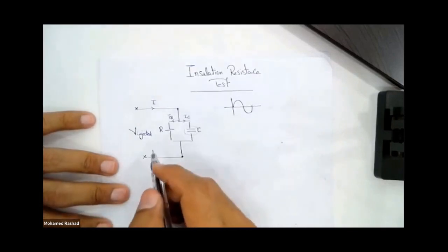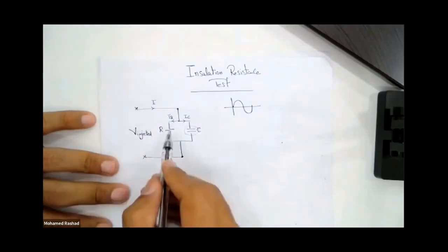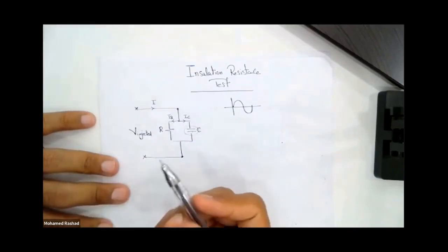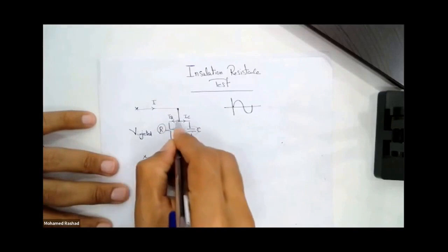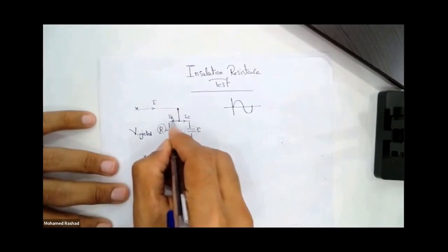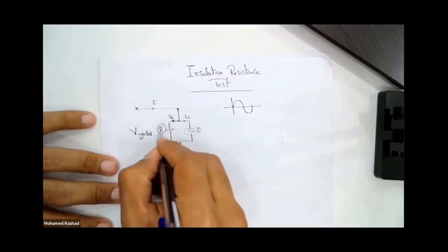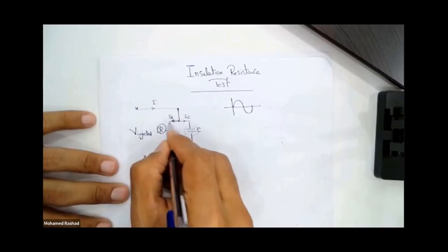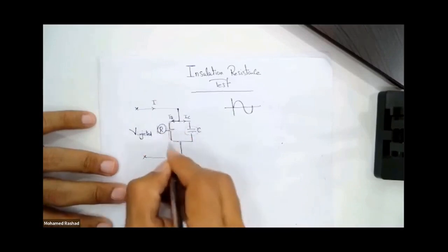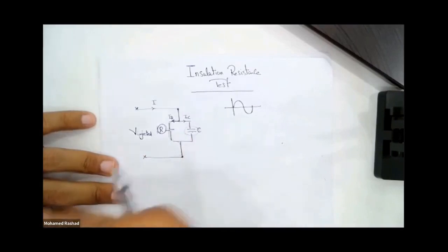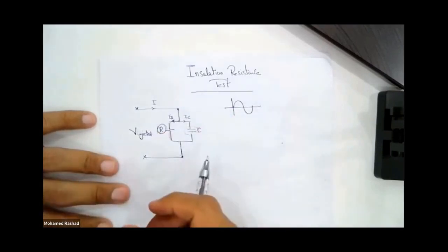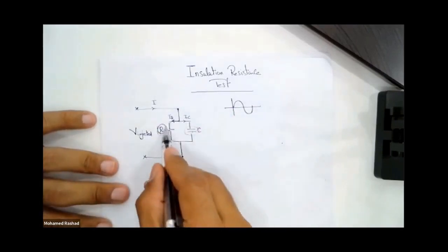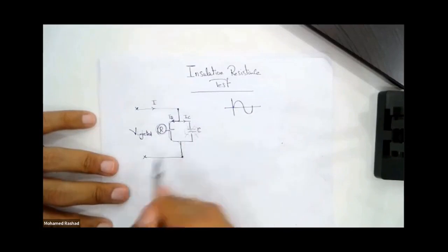Very nice. Okay, excellent. So what do I want now? I'll tell you what I want. Quite simply, which one of them indicates that your insulation has a problem? The leakage current. As long as this leakage current is drawing current from you, the lower this resistance is, the greater the current passing through the insulation will be. And consequently, what does this mean will happen? Breakdown.